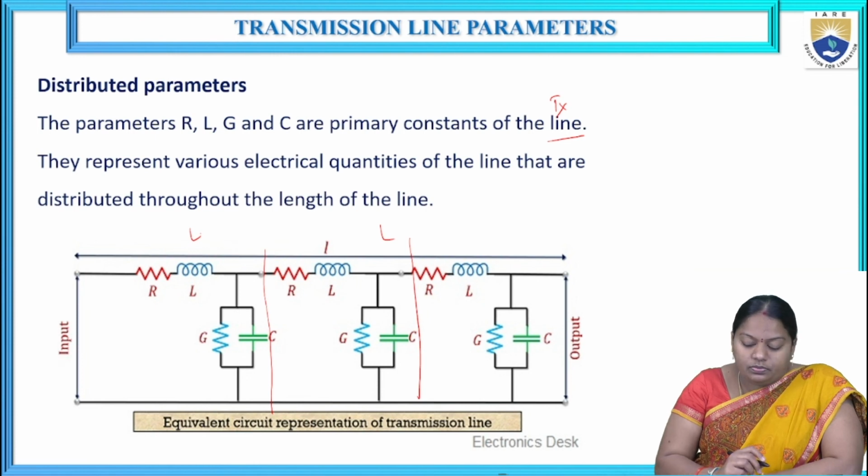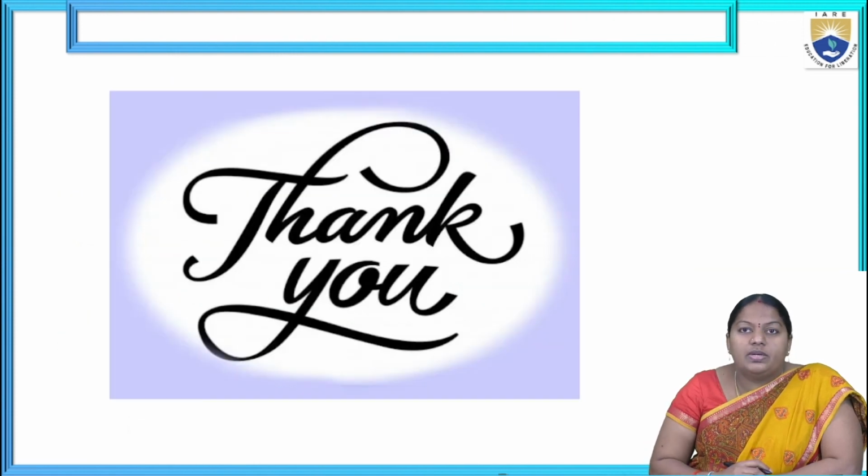Okay, so what we have discussed in this particular lecture is different definitions of a transmission line. Then the fundamental difference between transmission and propagation, and after that we discussed different types of transmission lines depending upon the structure and the frequency components. There are 4 classifications under these transmission lines: open wire type, coaxial cable, waveguide type, and, for the highest applications, optical fiber cable. Depending upon the frequency ranges, we discussed those 4 types of transmission lines.